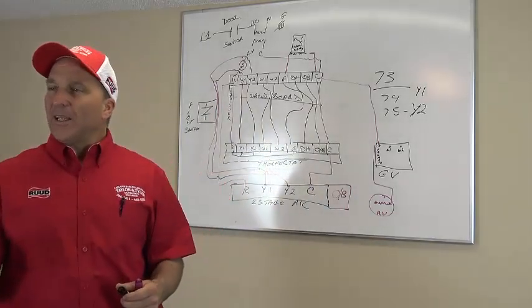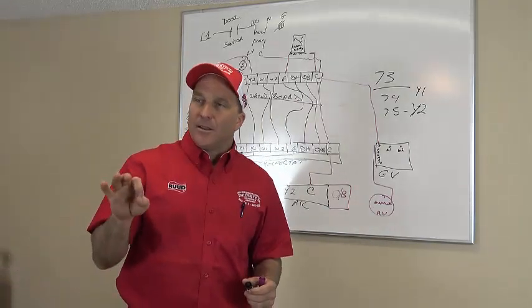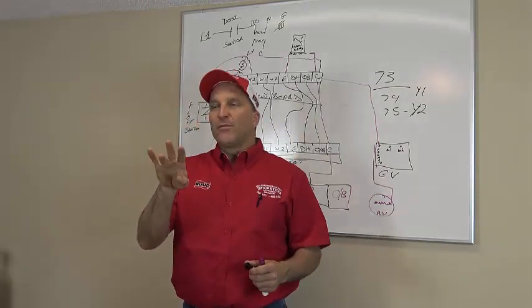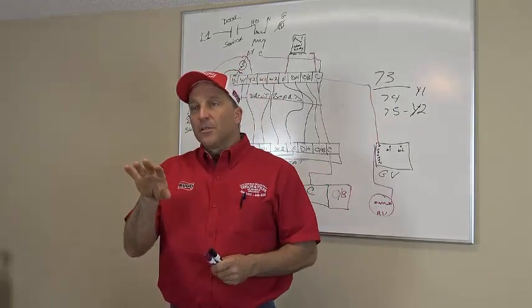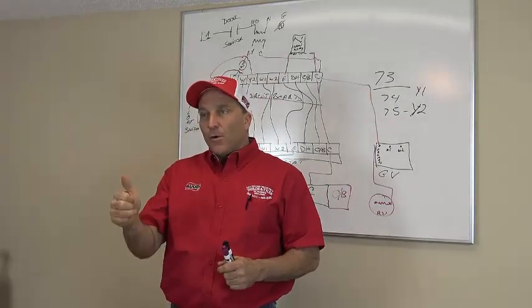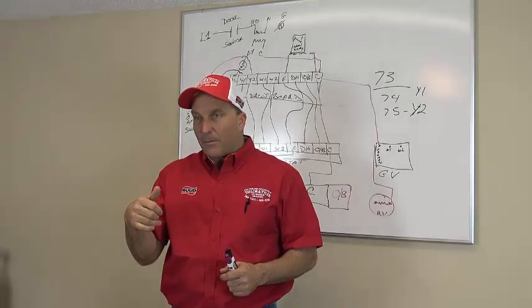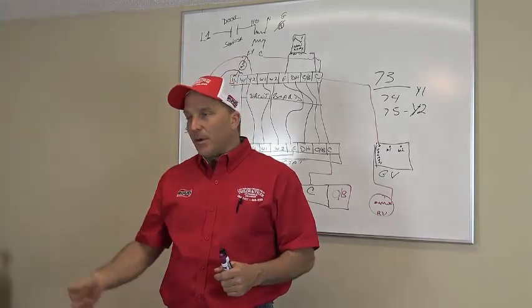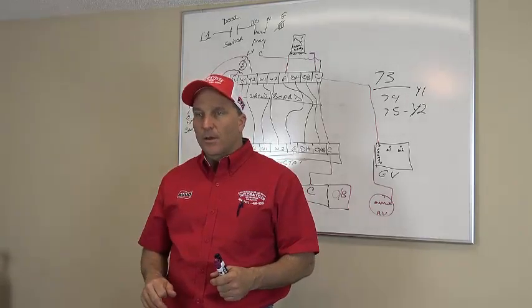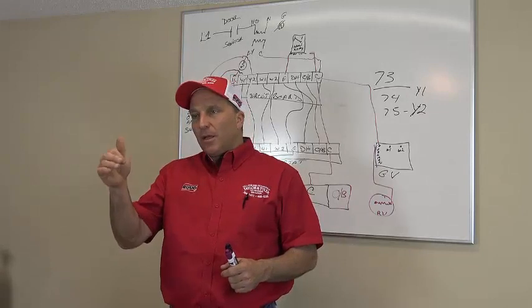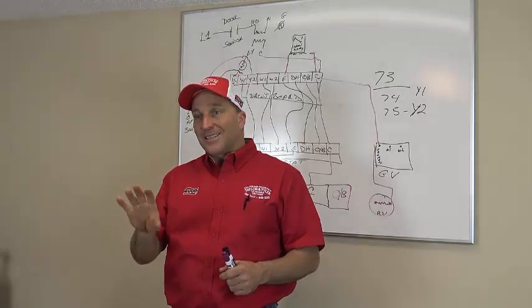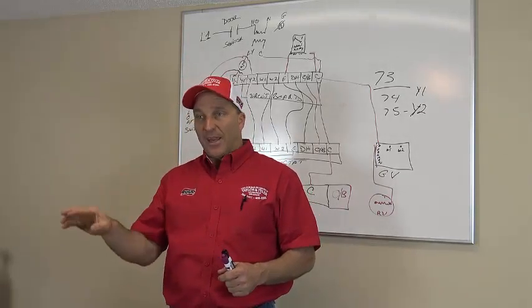Then when G is energized, there's a 3 or 4-speed fan motor on this particular system I'm talking about. It's a 4-speed split capacitor motor. Low fan is for heat. You might have a medium low. Medium low might be on the M1, which is a park. Okay. The G, it could be medium, low, whatever you want to put it on. It is a separate blower speed for fan.